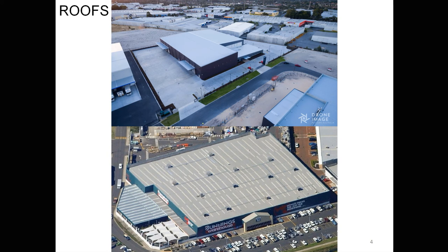What usually happens with these is that the gutters and downpipes are calculated from first principles, and then they're prefabricated. A lot of the metal shops around the place have really long folding machines, and they fold flat sheets of Colorbond or thin steel into the specified shape. That shape is designed for how it looks, but also for the capacity of water it's going to take, in terms of cross-sectional area.